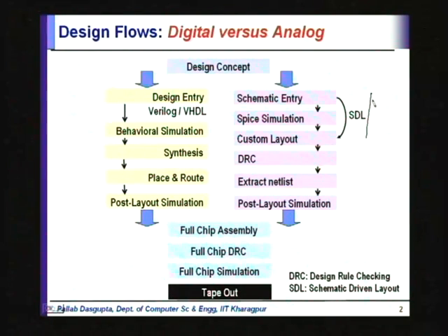Okay. The advantages of this is that you get a feel of the whole chip before you have actually designed the whole chip, because you can make the models and plug them together and then see how the whole chip works. That is one advantage. The other advantage is, as you start replacing each of those blocks with the corresponding designs, then the remaining blocks can be used as part of the test environment, right. So, test means pre-silicon test, not the post-silicon test. So, when you want to check a particular module, then the other modules are at behavioral level, so that the overall simulation speed is much faster.